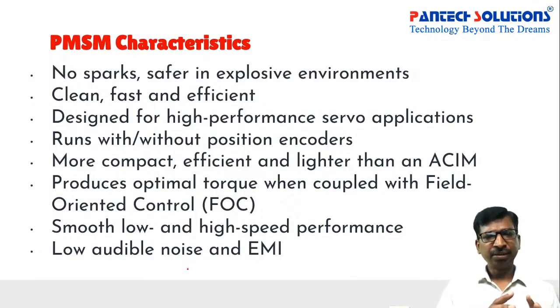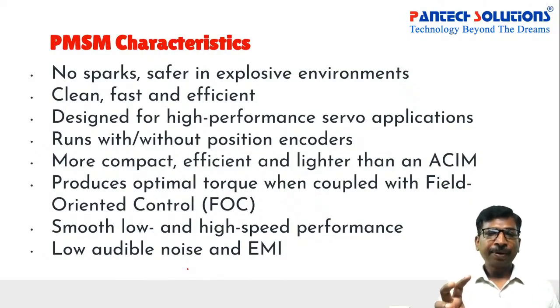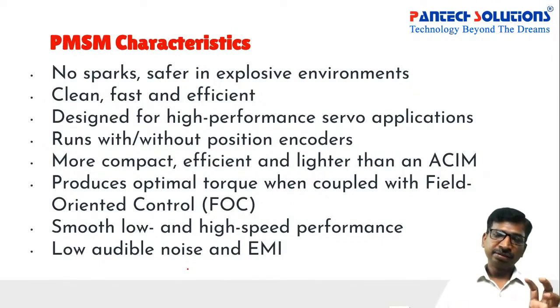And then, we can extend the speed to any range based on the motor dimensions. Similarly, for example, if you take a 1 HP PMSM and a 1 HP induction motor and compare the motor sizes, the PMSM will have a smaller size than the induction machine.